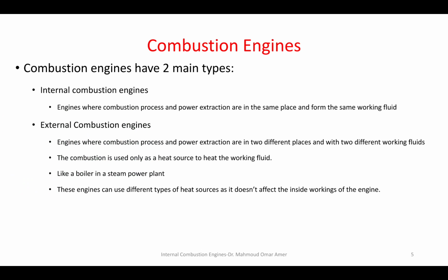So are the combustion place and the power generation place the same? No, the combustion is inside the boiler. The power extraction is in the steam turbine. Does the same fluid do both processes? No. The fluid that generates the heat is the fuel and the exhaust. The fluid that exerts power and generates mechanical power is the steam. So, not the same place and not the same fluid. So, this is an external combustion engine. Okay?